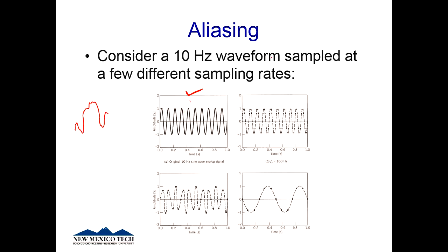If I sample at 100 hertz, the thing to notice here is it doesn't look perfectly like this one over here. But if you were to measure the frequencies here, it's pretty good. The amplitude's pretty close. So it's a pretty good representation. You got the right shape and you've got the right frequency in there. And so this was at 10 hertz, was our reality. And this is sampling at 100 hertz.